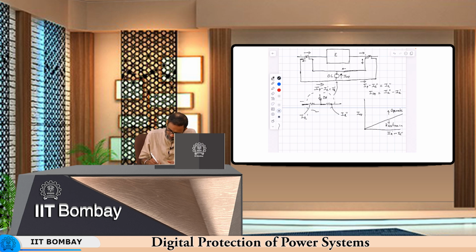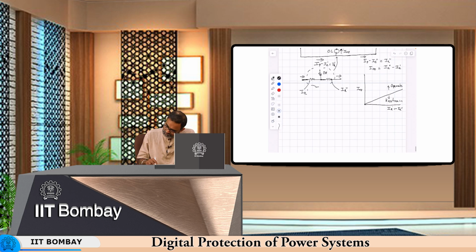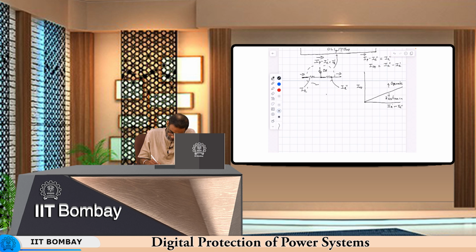In normal conditions this IR dash and IR double dash will be like this. If there is an internal fault, this could reverse. So the restraint goes down significantly, or it could even be 0. Okay, so that is why the operating point will now shift to the operate zone and the relay will operate. Okay, so this is how the normal current flow looks like in these operate and restraint coils.